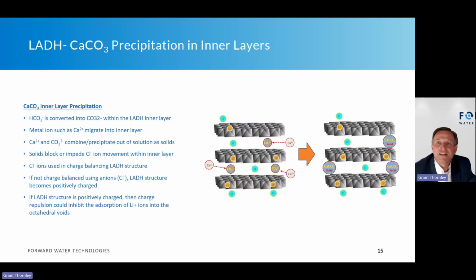So, contaminants of concern. Let's take a look at carbonates. In carbonates, we're going to say bicarbonates. So I have HCO3, and I have an alkalinity curve. At certain pH, I have alkalinity in my brine, which is very common. The concern is that with the alkalinity, the bicarbonate, which is HCO3, can be converted into a carbonate. So hydrogen comes off, and it'd be CO3 2 negative.